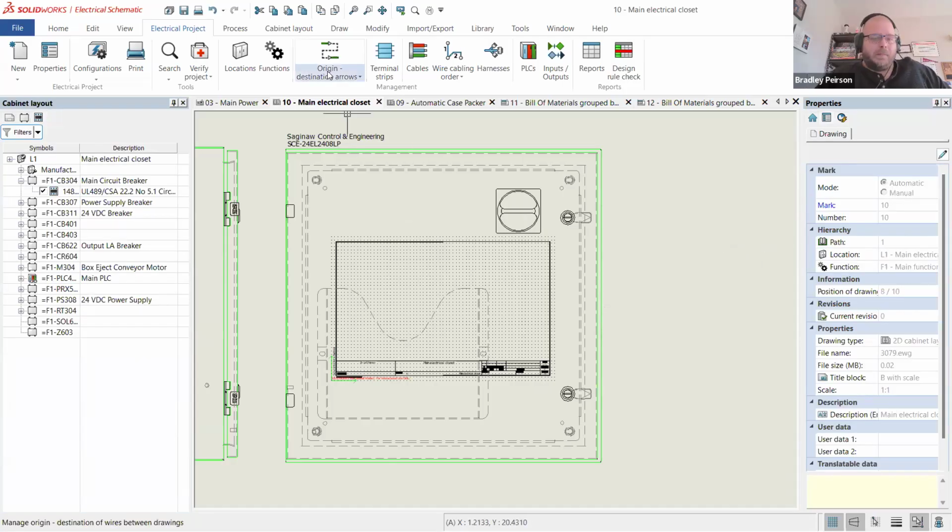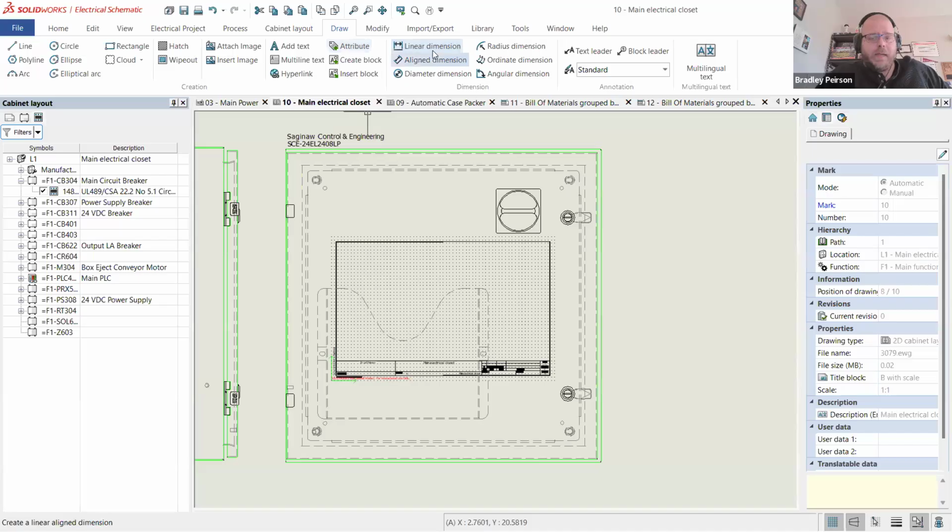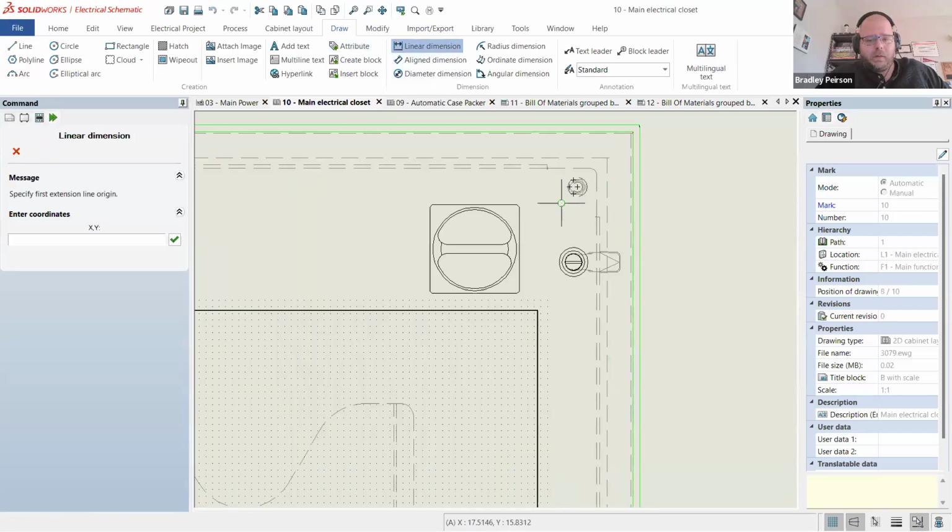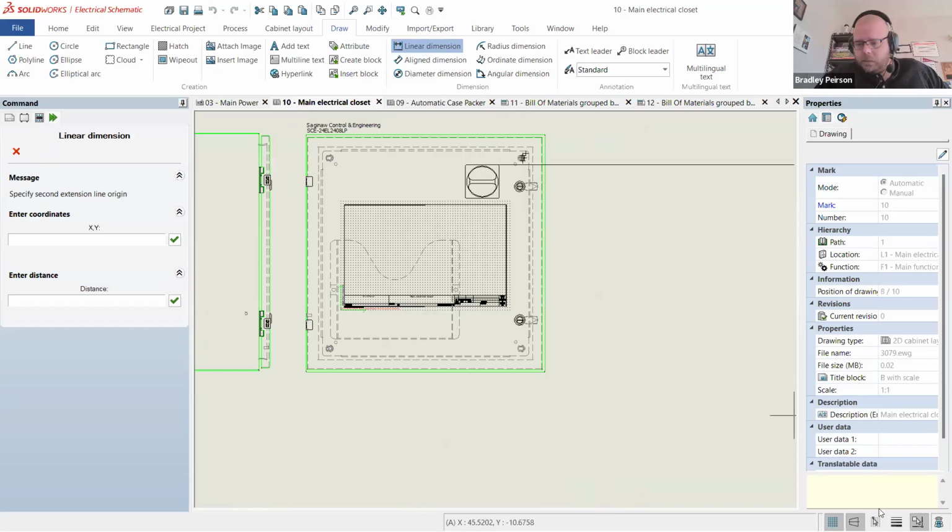And then, to dimension the guy, we need to tell somebody where to put it. On our drawing, we have the dimensioning tools, just like AutoCAD type stuff. So grab an edge, and what do we dimension from? My object snap should be on. The grid snap's off.